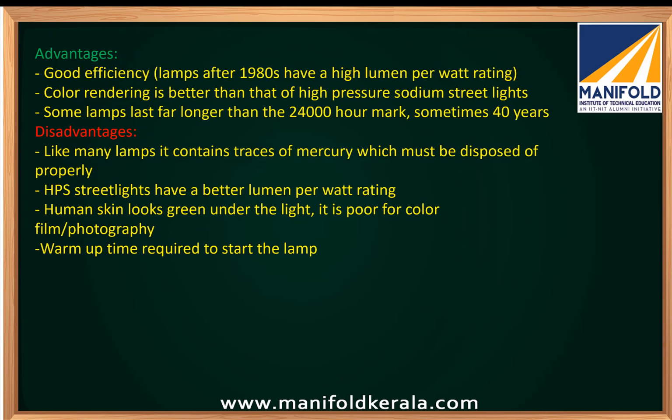Advantages: in the 1980s they used to have good luminous efficacy, but in later stages we got better options. Color rendering index is better than that of high pressure sodium lamps. Lamp lifetime is more. Disadvantages: it contains traces of mercury.